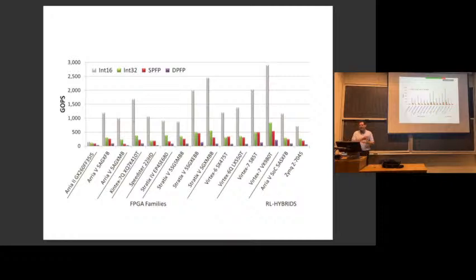You have this exponent that is moving around and making you shift your number. Shifters actually take a fair amount of logic. So floating point takes more hardware when you're building it out of the programmable fabric than integer does. Does that make sense? So small precisions, friendly for FPGAs. Floating point, not as friendly.